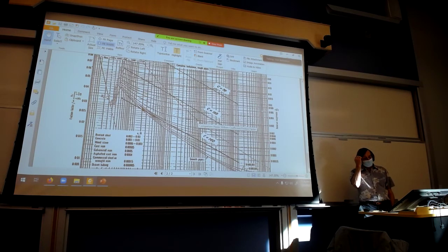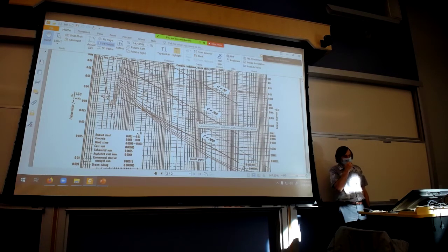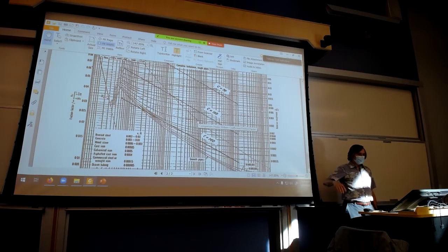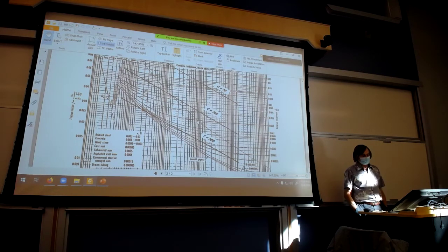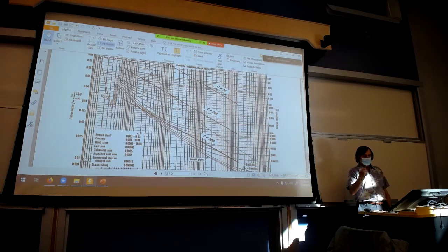And so you would think, by the way it's set up, with the Hazen-Williams roughness coefficient being constant, that it would be out in the turbulent zone where all the Hazen-Williams lines would be horizontal, but they're not. Basically, the best fit between Hazen-Williams and Darcy-Weisbach seems to be somewhere in the transition zone for a very, very narrow range of Reynolds number.